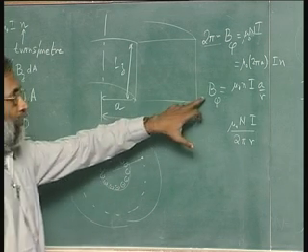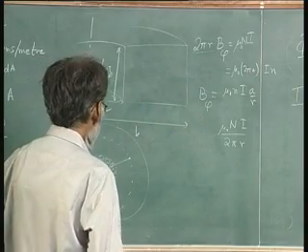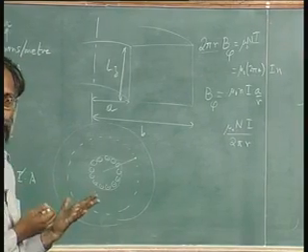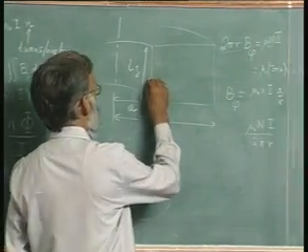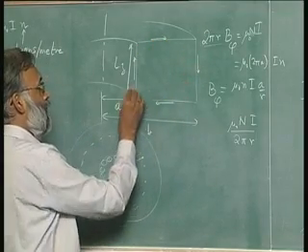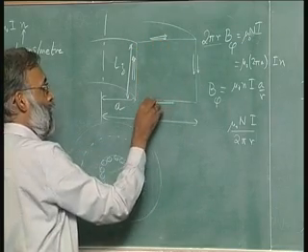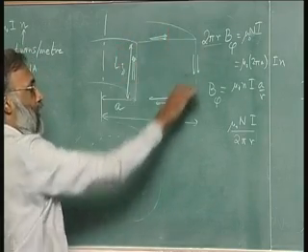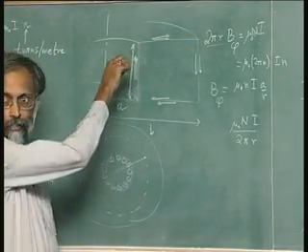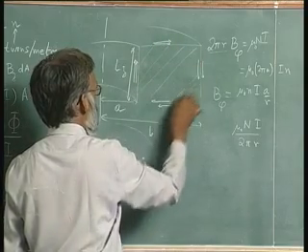Now, this is the magnetic field. We need the magnetic flux. Now, it is important here to understand what surface we are talking about. The current is flowing like this, and then it is coming back to the next coil, and so on. So, the current is flowing in the RZ plane. The magnetic field is in the phi direction. So, the surface we are talking about is the surface that links this coil.